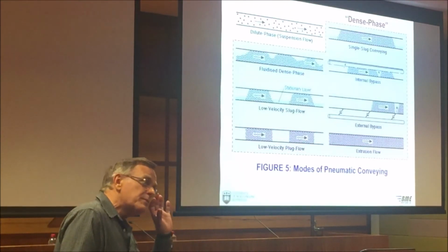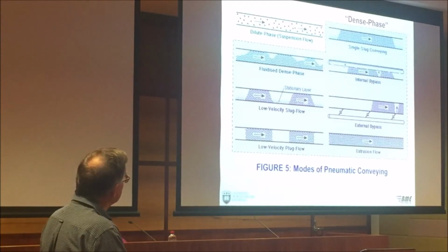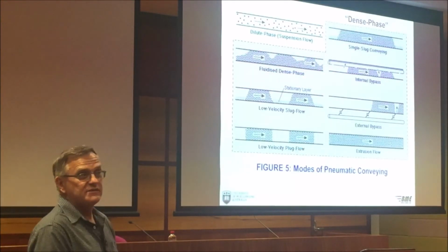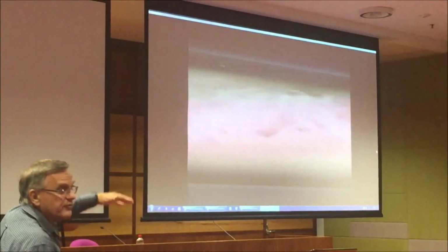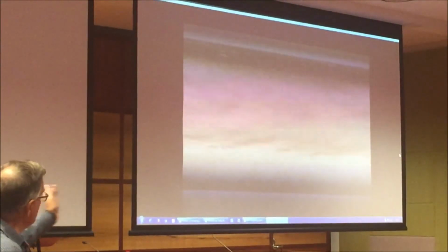And you just got to listen to the pipeline. That's all you've got to do. You'll hear the slugs going through it. You hear the fluidized dense phase. It's easier to keep going. The heavier it is, the more it wants to drop to the bottom of the pipe. But if it's designed properly, it'll be a self-cleaning system.